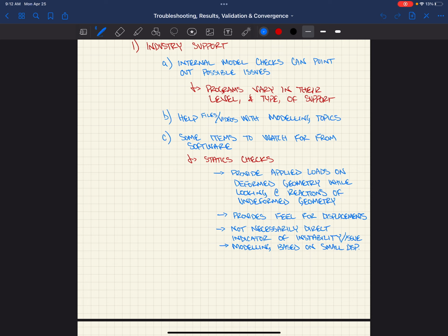Based on the areas. Why are those beams displacing so much more than the others? It's a relative displacement thing, right? It's a magnification of the displacement. The scale factor is right here, right? But this scale amplification is all relative, based on the displacements that are in this model to begin with, right? They make it so you can see it in the first place, and then you move it from there, right? So it might look like a lot.